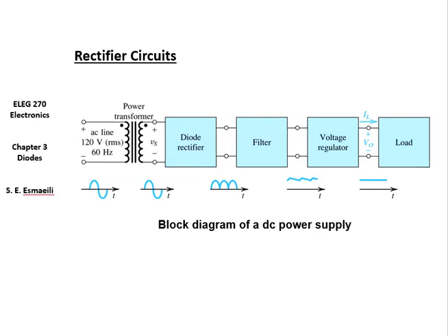Your phone chargers are actually a DC power supply, but you plug them into the wall, and you know that wall plugs give you AC. So why do I say they are DC power supplies? Because inside them there is a rectifier. A rectifier is a circuit that takes an AC signal as an input and gives you a nice clean DC signal at the output.